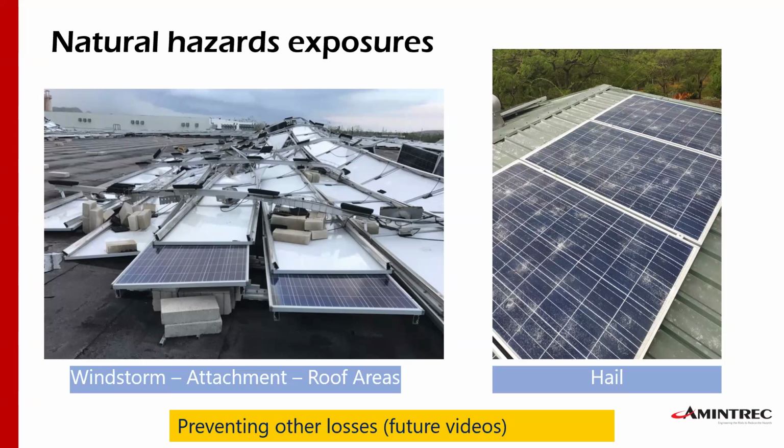I'm not just talking about the roof, because the same analysis for a windstorm evaluation for a roof cover has to be conducted for a photovoltaic panel installed on the roof. Otherwise, they will blow off. They can end up in other areas or over some high voltage lines and create a short circuit, and that's going to be a huge problem.